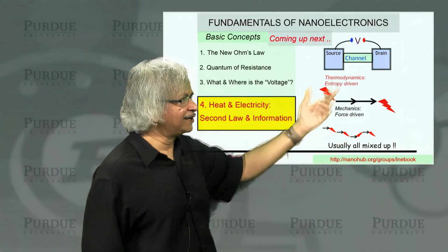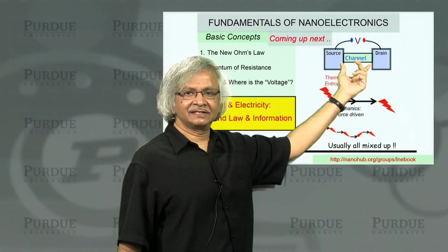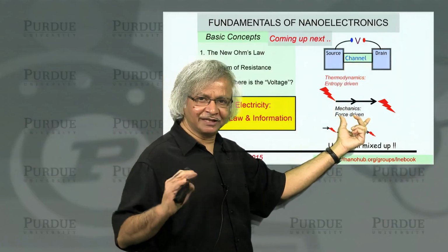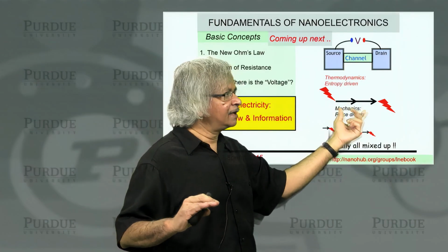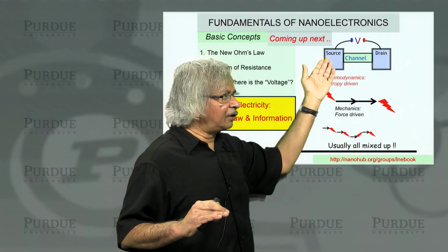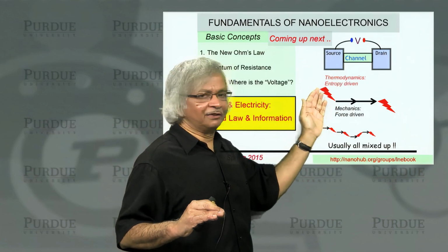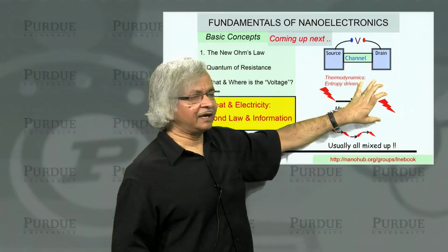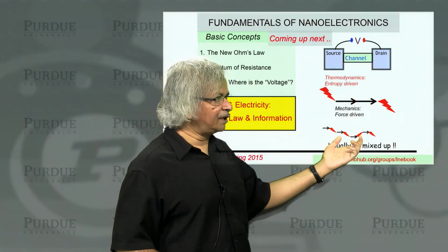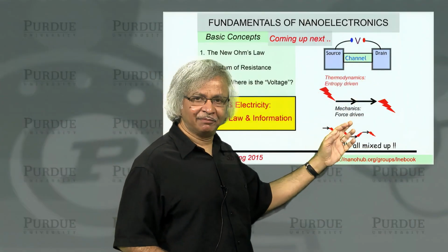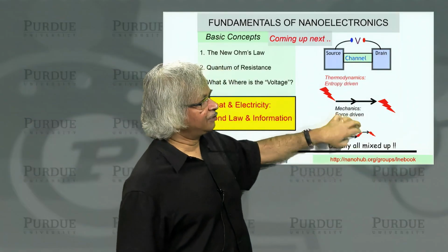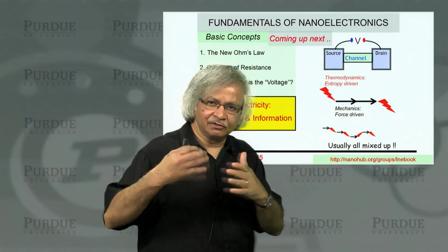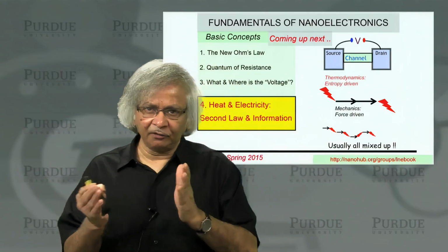That is, you assume that the channel is described by pure mechanics, no inelastic processes, whereas all the entropy-driven things, this thermodynamics, is associated with the contacts. Whereas in practice, of course, it's all mixed up. But what I tried to explain is you could idealize small units like this, and that gives you a lot of insight in terms of how current flows.